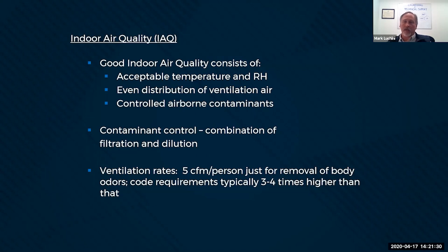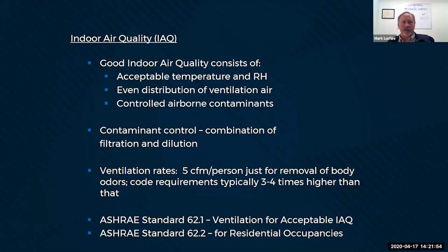Now, those are peak values. You can do less than that if you have a control scheme called demand control ventilation and you're actually measuring the CO2 in your space. You can reduce those numbers as long as you have the capability, as CO2 rises, to get up to the code levels of ventilation. And all those levels are basically spelled out in ASHRAE Standard 62.1 and 62.2. ASHRAE, everybody knows what ASHRAE stands for? American Society of Heating, Refrigeration, and Air Conditioning Engineers. I was a proud member for many years.